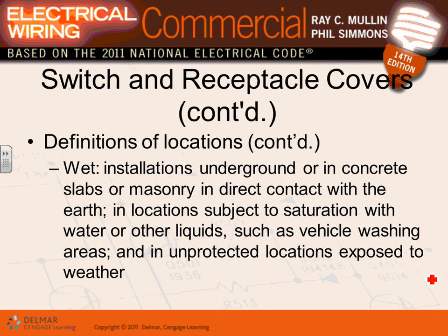Wet location, the key word for wet location is, guys, saturation with water. Installation underground is called wet location. Concrete slab, of course, in direct contact. Masonry, in direct contact with Mother Earth. So the key word, when I teach this, I say the word saturation with water. Any place that there's saturation of water, it's a wet location. Car washing places, right? Any place where they use water on a regular basis, inside or outside, obviously outside because of the rain, it's called wet location.